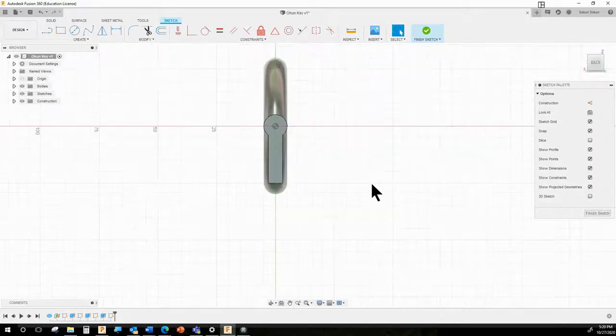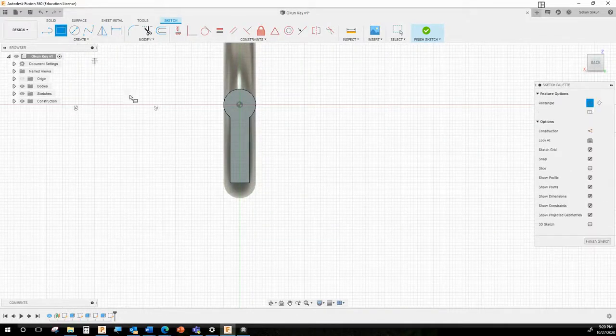And if you need to, you could zoom in for this because you're going to be making a little rectangle. So R for rectangle, or make a little rectangle. Make sure you got that little corner and come up and to the side. And I just happened to draw it exactly right. You want it to be 6 by 3. Type it in if you didn't happen to get incredibly lucky like I just did.